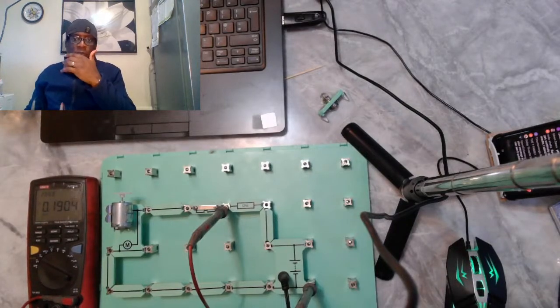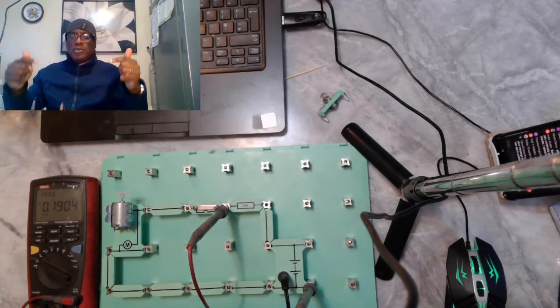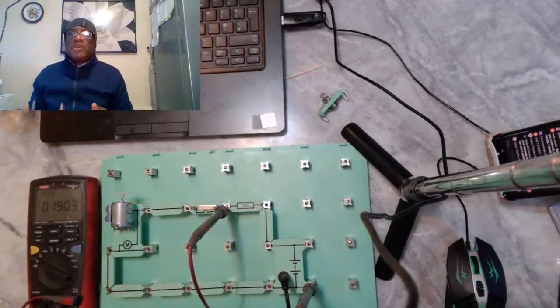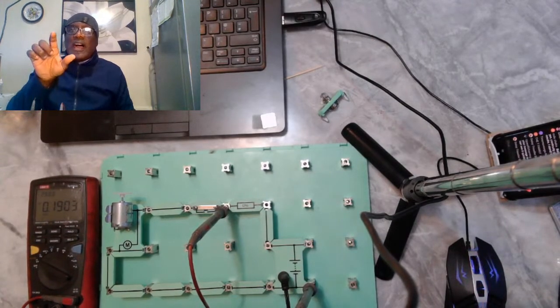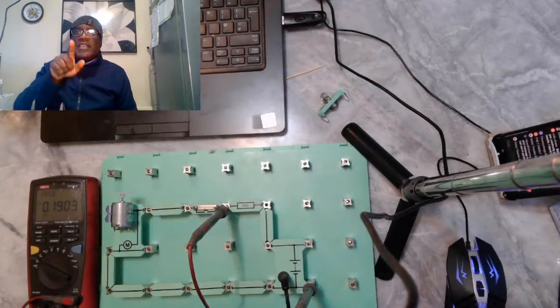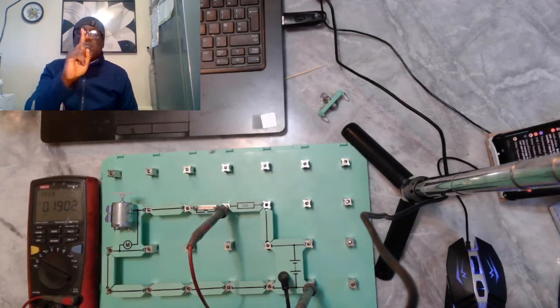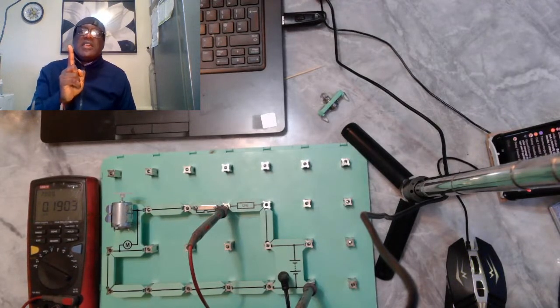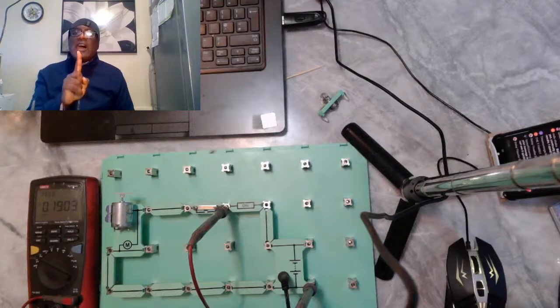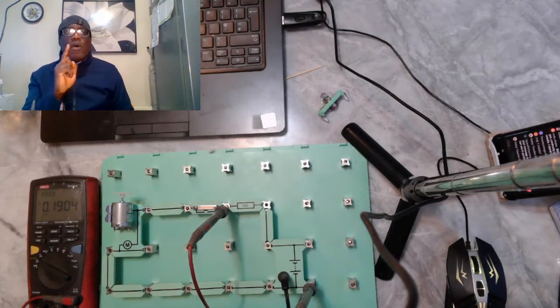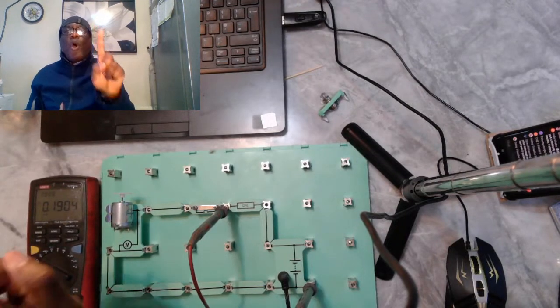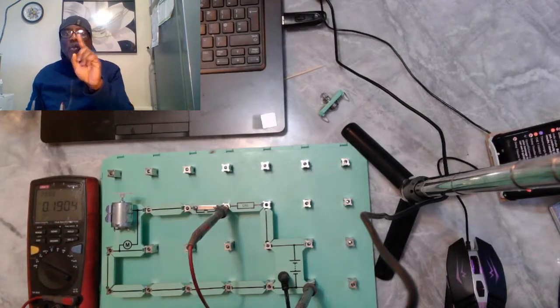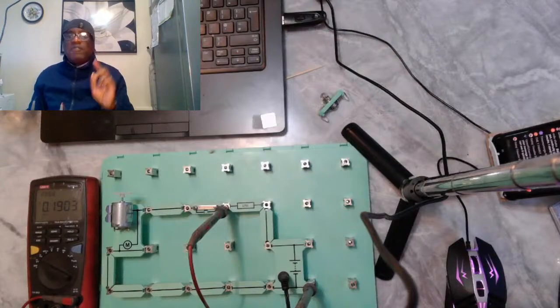And then you find that when you check for continuity and you have got an open, your meter will read 1. Your meter will be showing the symbol 1. Then you know that that's infinity resistance, so you have an open. Or some of the meters will show OL. When you see your meter is showing OL, it means that's infinity as well.